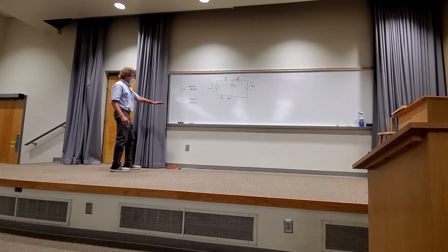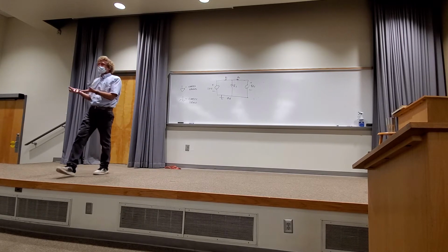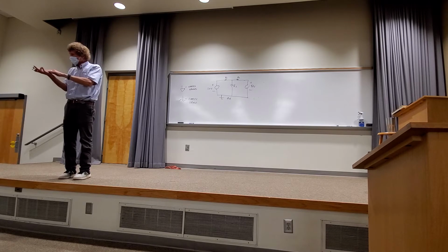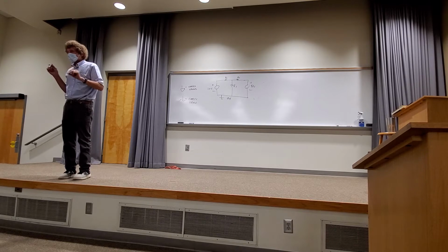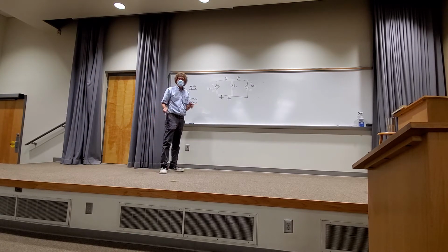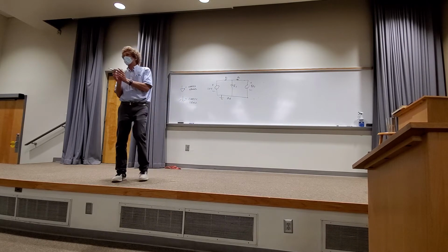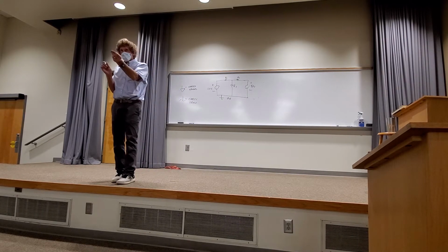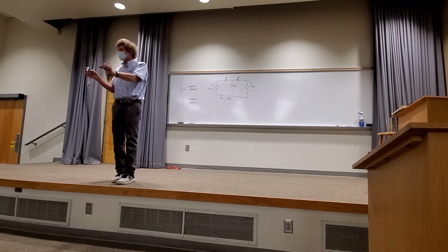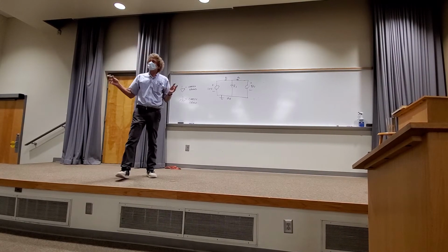This is a chassis ground. Y'all know the term chassis? Usually it's something that houses stuff. Metal boxes that have a lot of things in there are often grounded, and everything is referenced to that ground. You take the negative terminal of your voltage meter, and you just use an alligator clip and clamp it to the chassis ground. Then you go around measuring the circuit, the voltages. That's what voltage is with respect to a chassis ground. This is a circuit ground. It means for an individual circuit by itself, on like a breadboard or something like this, that's the ground point that you would put your lead on the meter. That's the way I like to explain this because it's applications, all right? That's it, and they all fundamentally mean the same thing.